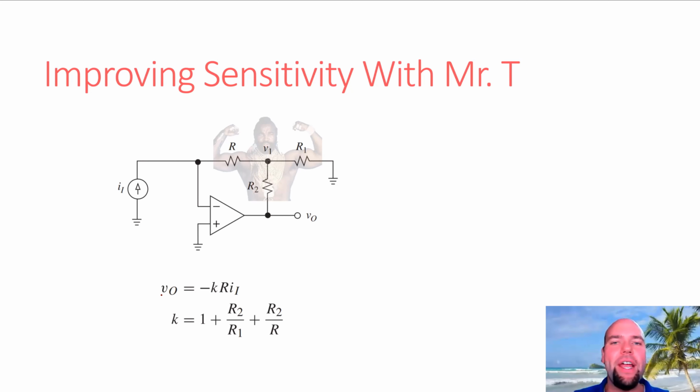So the basic idea is the same, right? The whole idea of feedback and op amps is the way you get bigger gain in an op amp system with feedback is to have greater attenuation in the feedback network. If you only allow 1/1000th of a signal at the output to come back to the input to be compared against your input signal, then your op amp is going to have to amplify it by 1000 to make that 1000 times 1/1000 equal 1, right? So the way feedback works is the more you nuke a signal on its way back to the input, the greater the op amp will have to work to produce a large output.